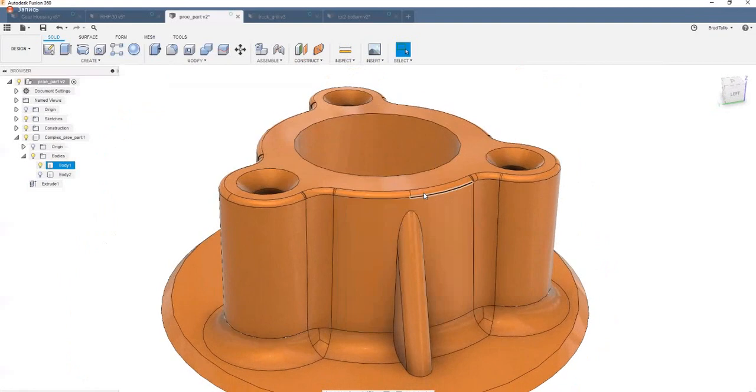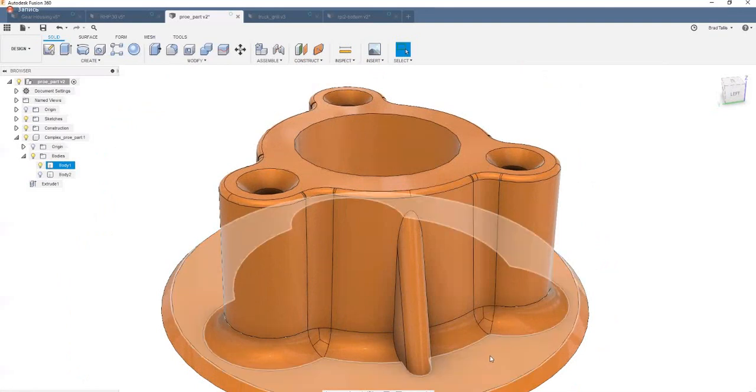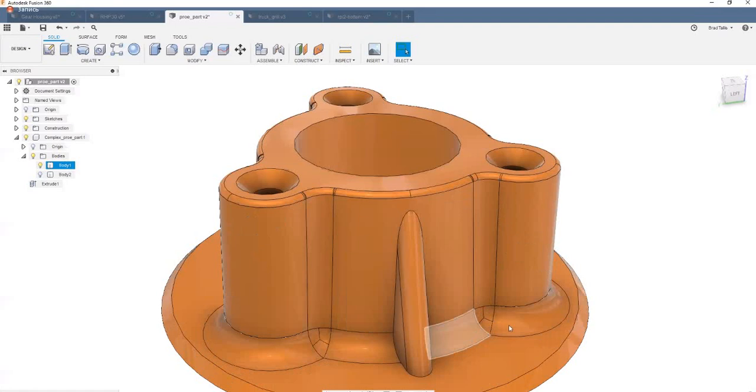In this case, it's actually better to get rid of as many of the fillets at the same time, because we know these fillets are touching these fillets, which are touching these fillets, which then end on a flat face, which should be okay. It's probably something to do with any of these fillets here. So we're going to remove all of those at the same time.